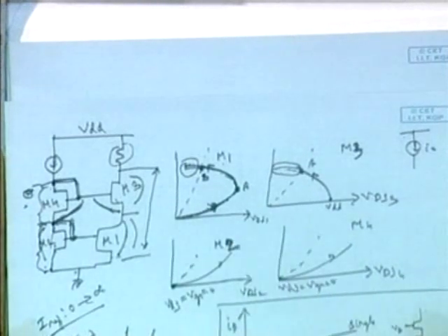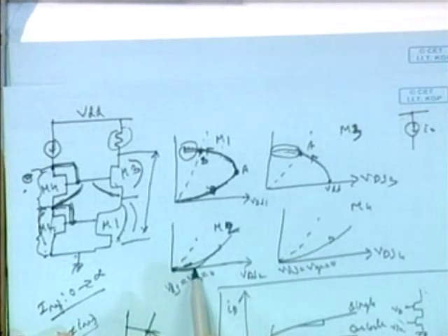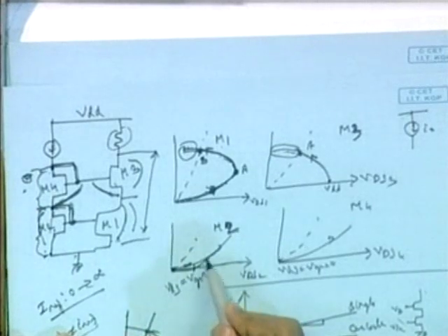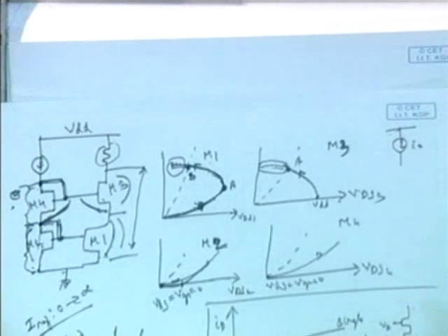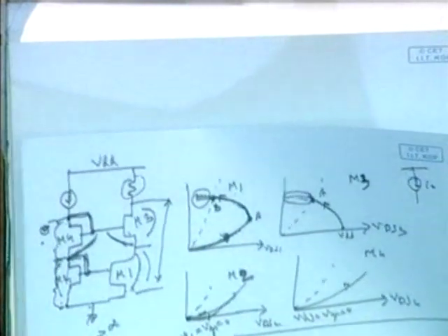Okay. After that, sir, the transistor will become on only when VGS has crossed VTH. Yeah. No, actually it will start from this. So up to some point, no current will be there, and after it crosses the VTH of the respective transistor, the current will start to flow. Actually, you can verify all these things using simulations during your lab also. It is easy to verify all these things. Okay, this is clear.